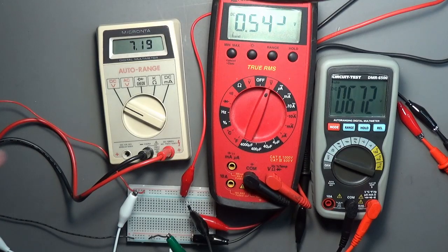So we're up to 7, 8 volts. We're losing about half a volt across our diode now. So that's something to remember about diodes. They need a minimum amount of voltage to work, and there will be a voltage drop across them. So they will basically steal some of the voltage. So something to keep in mind when using diodes.